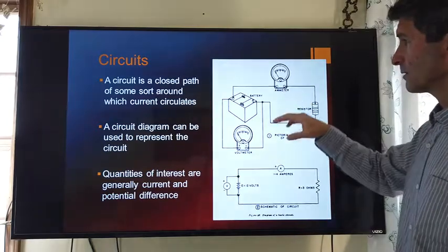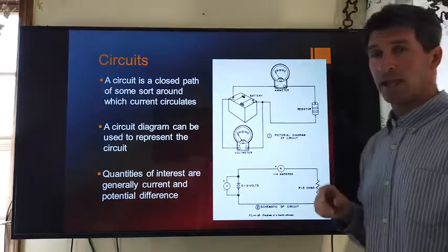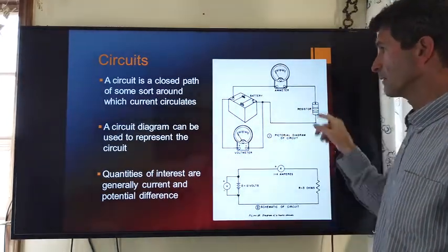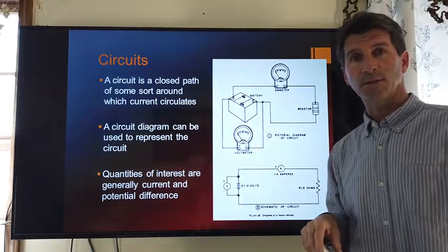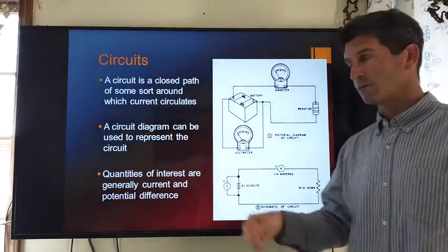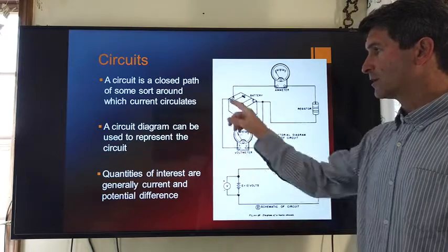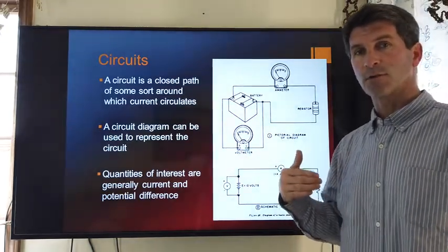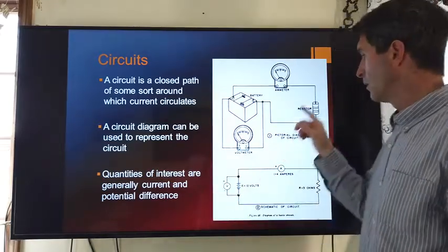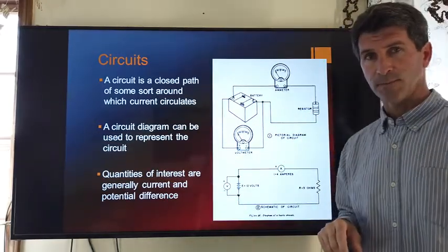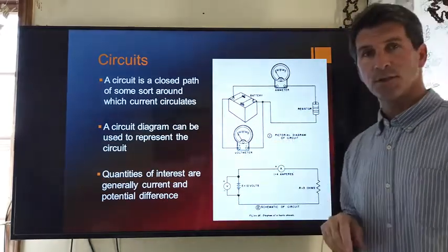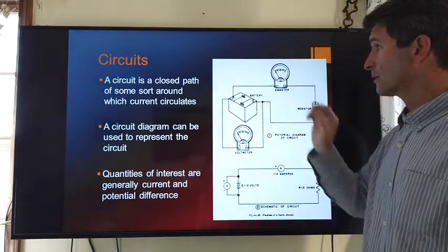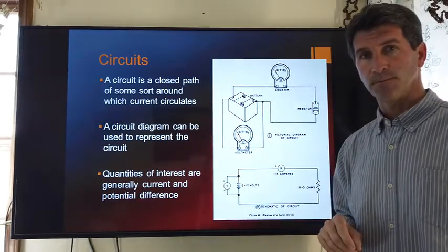So in measuring current, we use an ammeter. It tells us how many amps are flowing through a particular object. So current is through. For a voltmeter, we talk about across. What is the potential difference for the charge to cross from one terminal to another, or from one side to the other? Okay, so voltage is always measured across, current is always measured through.